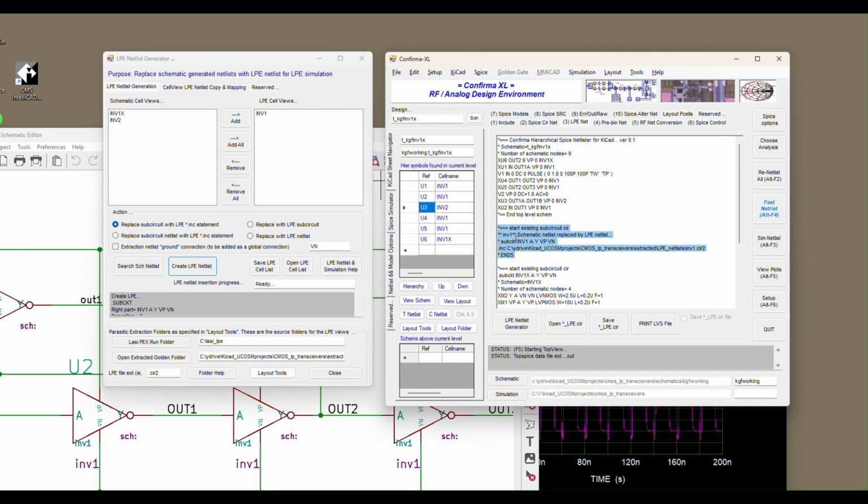So now that previous portion of the netlist is commented out, and it has added this include pointer. This include pointer is to a Spice netlist file, which contains the extracted view. It has parasitic Cs and parasitic Rs that came from the netlist. Whatever layout tool you have, that's usually where the extraction is done.